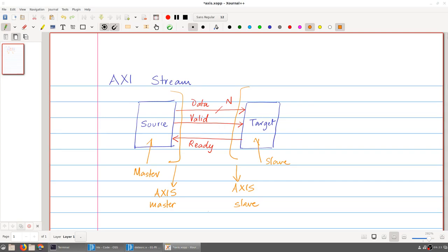Now for our purposes, we have already generated the input data in a hex format using the datagen script that was used when we set up the FFT HLS project. We would like to load this same data into some kind of Verilog module that can then act as an Axis master and give out this data.